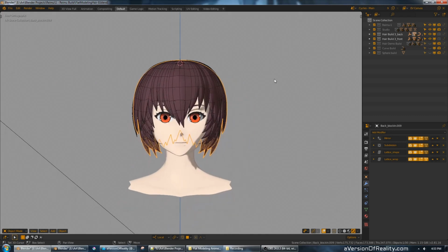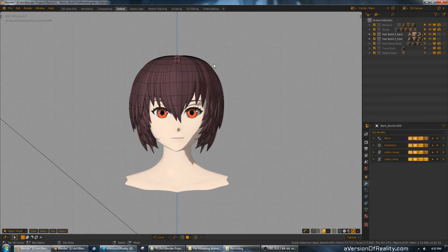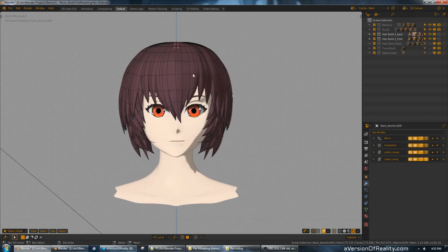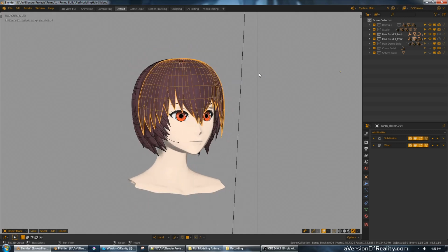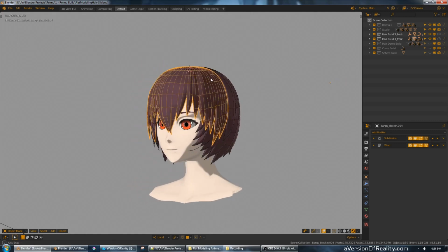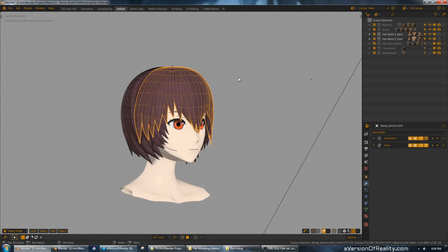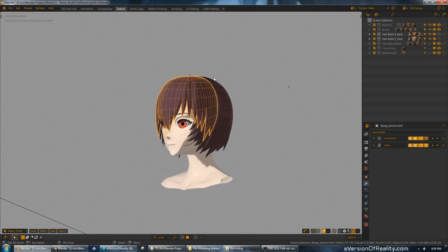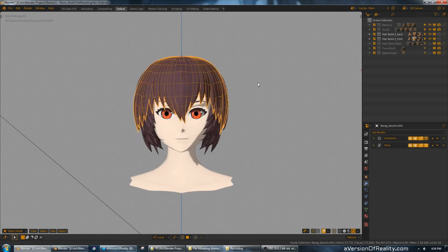If you want to rig your hair, there's lots of ways to do it that I won't really get into detail on here, but the way I'm planning to rig this sort of hair in the future is to use the block-in plane we made at the very beginning, chuck that in the same lattice as the hair, and use that as a rigging mesh with either the surface deform modifier or solidify it into a mesh deform cage, and chuck this hair in that, and then bone rig or maybe cloth sim that simpler mesh. So that will make it much easier to deal with things. So I think that's it for now.